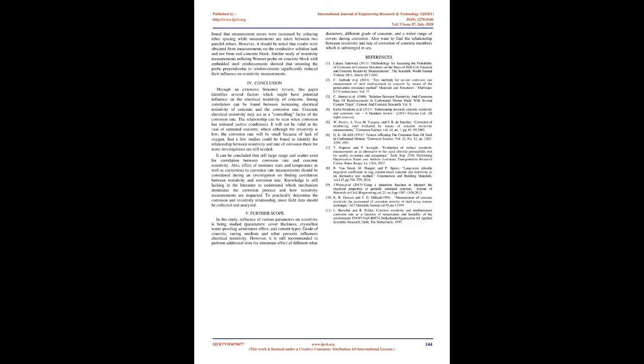C. Presence of rebar. S. G. Millard and K. R. Gowers [10] utilized an experimental setup with steel rebar in tanks filled with conductive medium solution, along with finite element modeling, in order to study the effects of concrete cover thickness as well as rebar diameter and spacing on concrete resistivity using a 4-point Wenner probe. According to this study, the distance between the probe and embedded rebar was found to be the main influential parameter when measurements were taken on top of the bar. It was also reported that rebar diameter is not impactful in its disturbance.